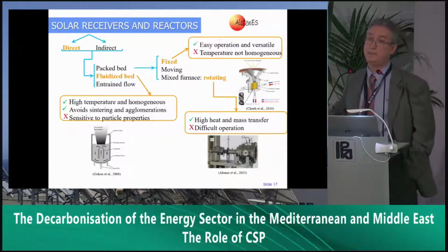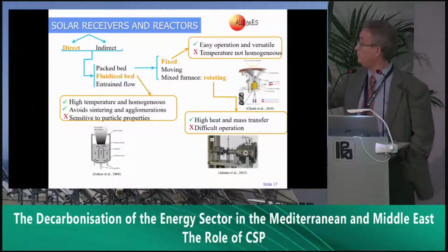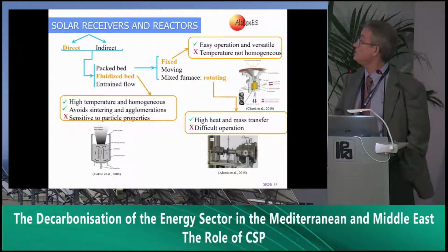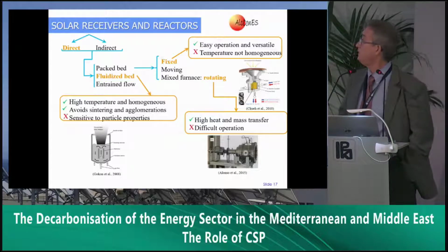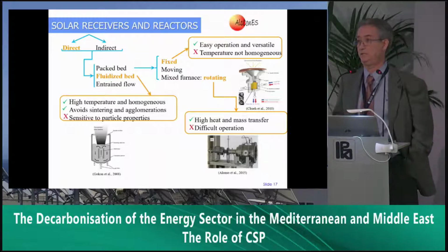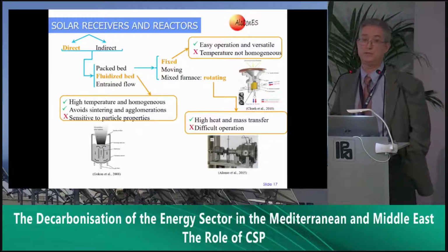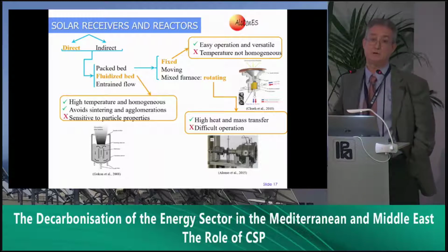And finally, apparently the ultimate solution, and the community is more and more moving now to particle receivers, because you can guarantee more homogeneous conditions and better heat transfer, but it's extremely sensitive to the particle properties. In some cases, believe me, it's a real nightmare to control the conditions of irradiation, temperature and fluid dynamics of the process, because depending on the geometry of the particles, the density, etc., everything changes dramatically.